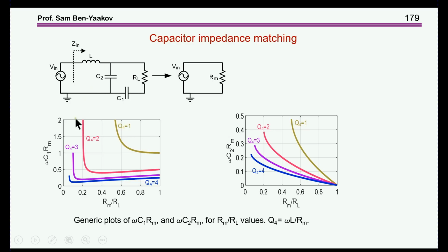This network is changing the impedance that you see here. Now, you can do the same thing within a converter, a buck converter, but then, of course, you need the switcher, etc. There's power loss associated. If you use these two capacitors, you may need to change this ratio of capacitors to optimize it.